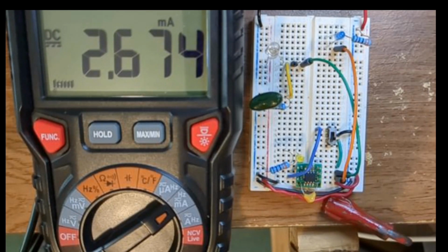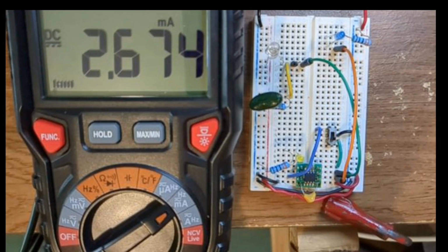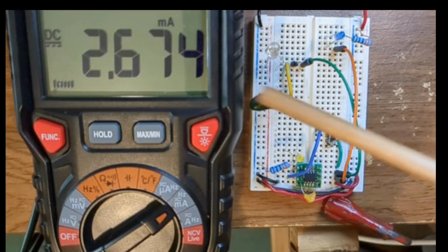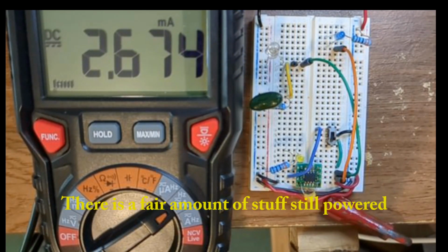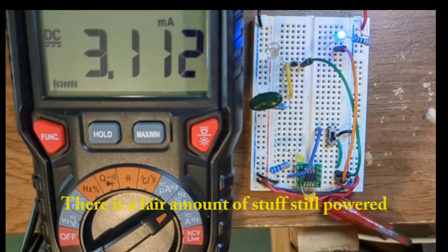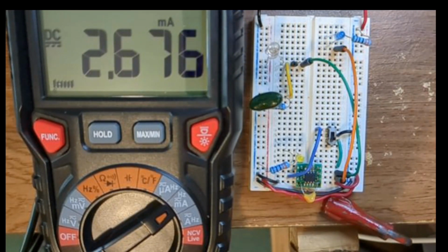And so on the setup here, you can see there's a blue LED, and when that blue LED is on, the core is awake. When the blue LED is off, the core is in standby mode. And you can watch the power consumption change on this multimeter over here. So when the system is asleep, as it should be in a second, the power consumption is 2.67 milliamps. When it's awake, the power consumption increases to 9.78 milliamps.